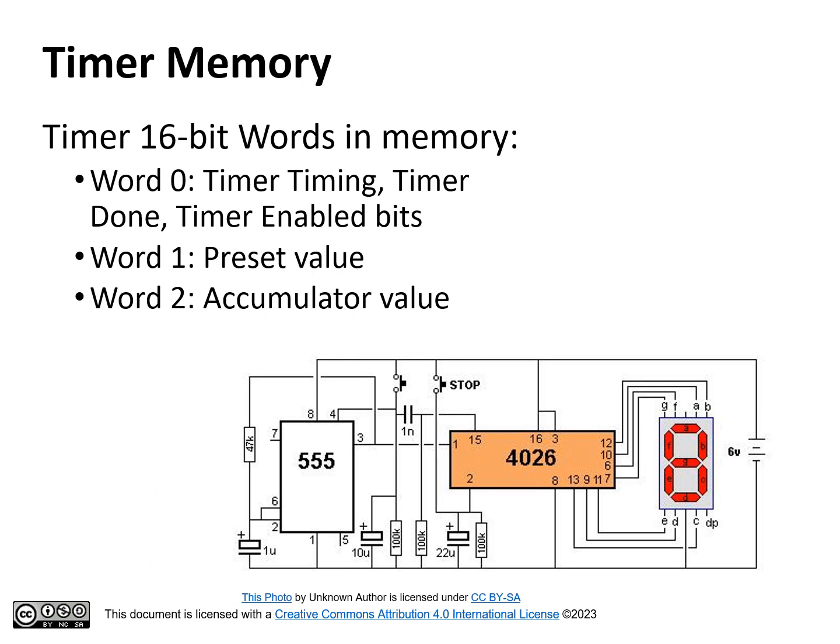Another important piece of information is the time base by which the timer is timing. There are 3 options here. 0.001 seconds, or a millisecond, 0.01 seconds, or a centisecond, and 1 second. The actual preset time interval is the preset value multiplied by the time base.